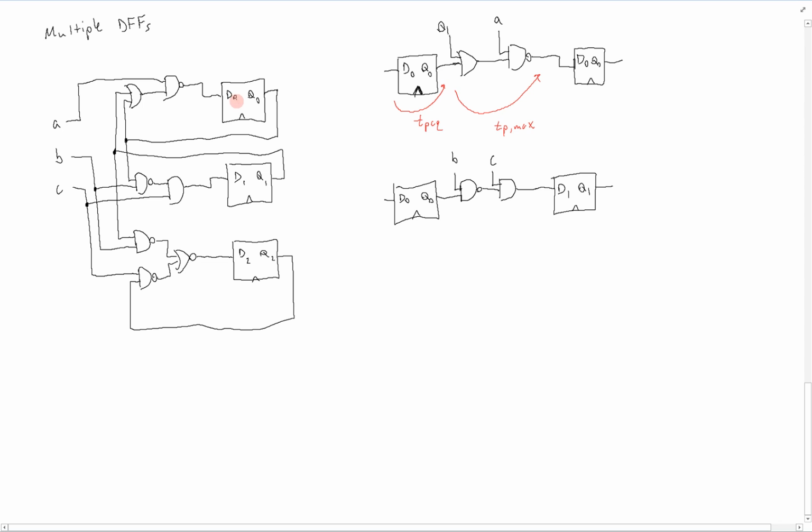it's going to be very analogous to the first one over here, where the input to the OR gate now is the output of the first flip-flop, Q0, and again we go back to the first flip-flop. And then there is another path going to the third flip-flop from the second, which goes through here with these two NAND gates and the NOR gate and into here, and from the second flip-flop back to itself around that same similar path.